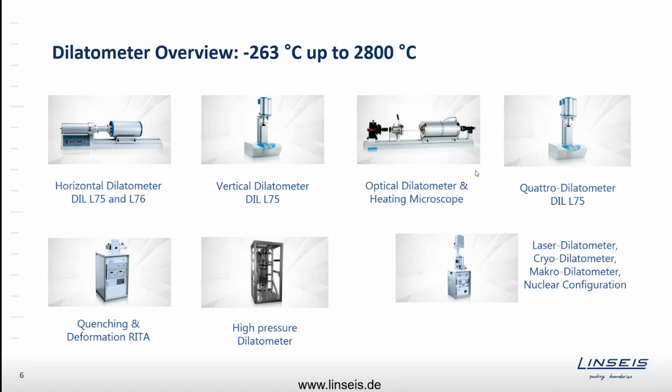For quality control issues and for high throughput, we have so-called quattro dilatometers, which is a system that can measure up to 4 samples simultaneously. So you have one furnace, and in the furnace you have 4 sample positions and 4 push rods. This was designed for high throughput quality control, and you can measure 4 samples at the same time using different furnaces, even so you can have a high or fast throughput.